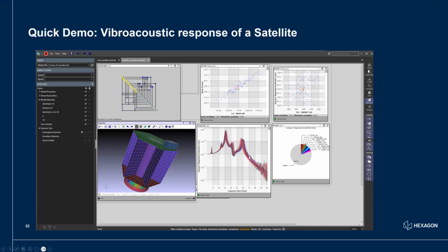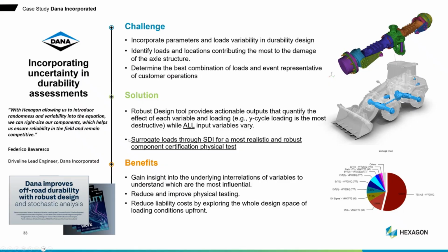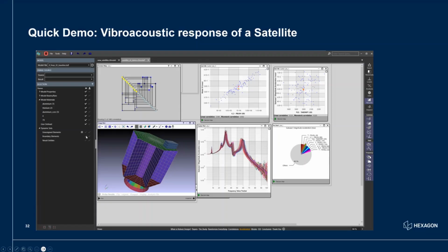Or maybe we do it more realistically. In this case, we do a fatigue analysis. We realize that this particular peak is very influential, because it's going to be a wide band loading. This might be very influential to the end RMS and the moment of the power spectral density, and it will negatively affect the vibration results, and especially the fatigue results. And we might want to find a way to reduce this peak. So we can use robust design to go back to this, and even, to be honest, adapt robust design, so we have a way to convert this problem into a recursive iterative problem that does adjustments to certain design parameters to meet a certain target.